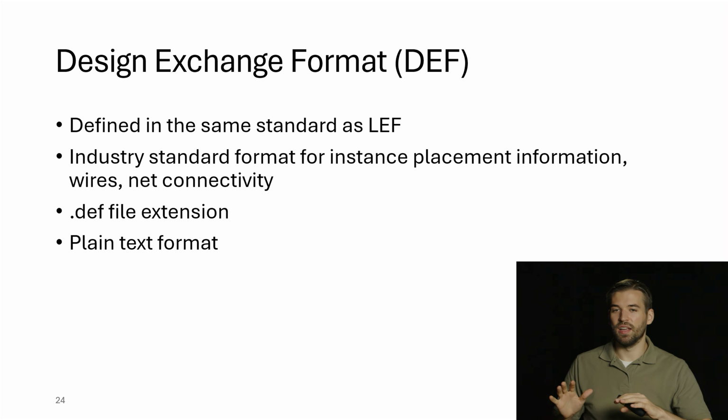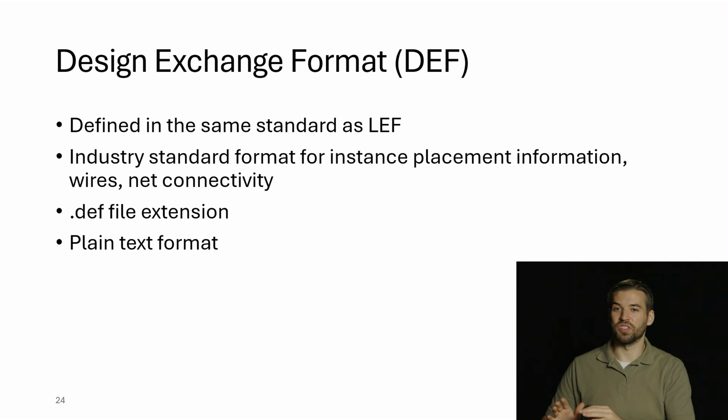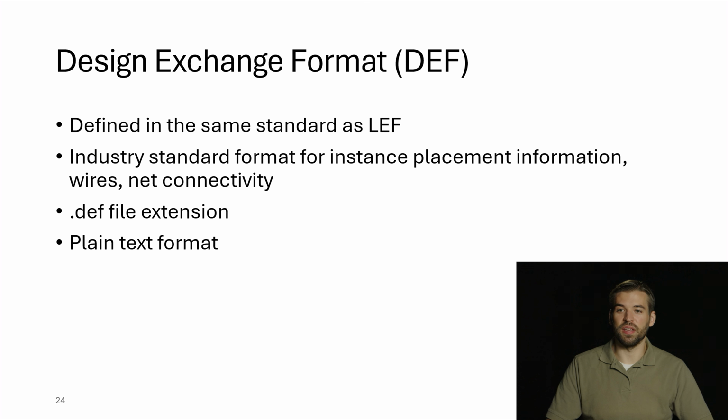We had information about the masters, and now DEF is going to tell you how all of those are actually used. What is in your design, what are the actual instances rather than just the modules, just the masters, and how are they placed and how are they connected. In this case, the file format is going to be in the .def file extension, and again this is a plain text format, so you can just open this up and read it in plain text.